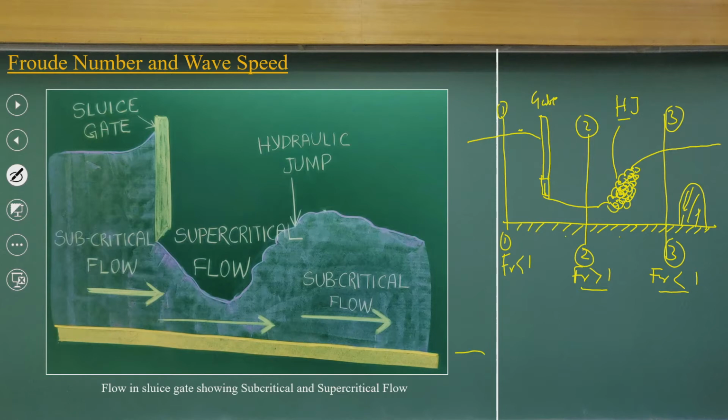We try to do the mixing process with just creating a hydraulic jump. Bigger hydraulic jumps you can see, and smaller hydraulic jumps also happen in real life. You can see when the flow changes from supercritical to subcritical regions. That is the reason we will have a hydraulic jump, and also we will have energy losses.